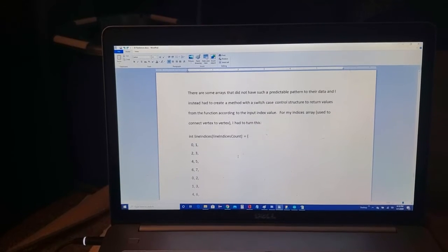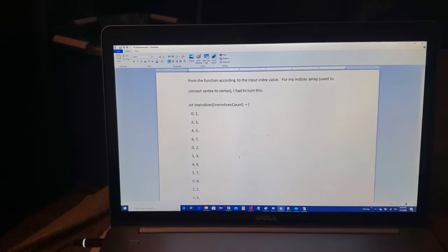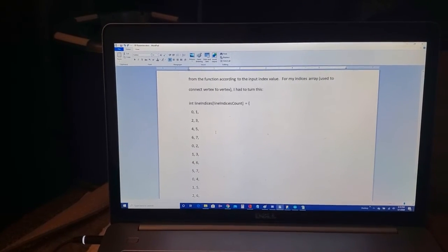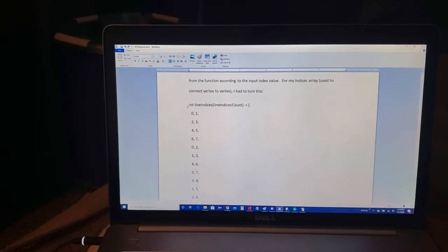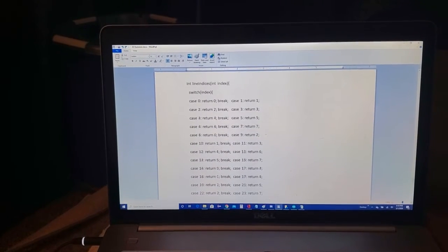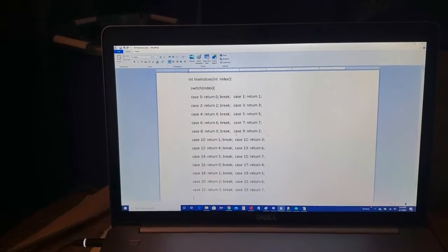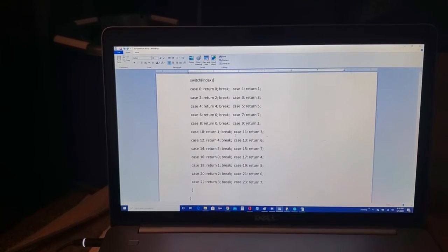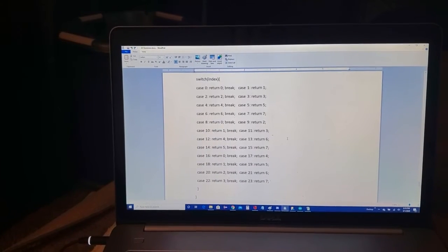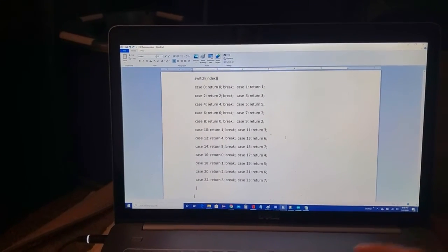There were some other arrays that I was also unable to store in the Arduino's memory. And so instead, I took this array here and I made a switch case structure. It used up instruction memory instead of the local variable memory, and there's a lot more instruction memory. So even though this is less efficient, there's a lot more memory available to store it this way.